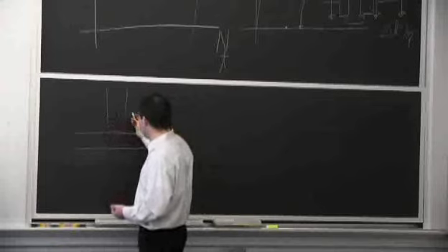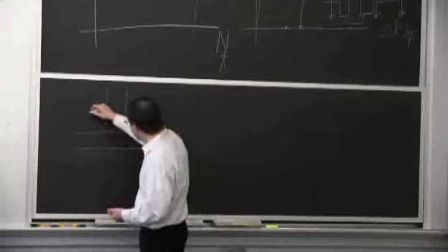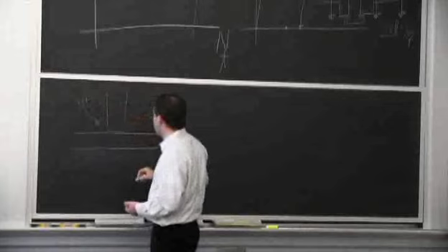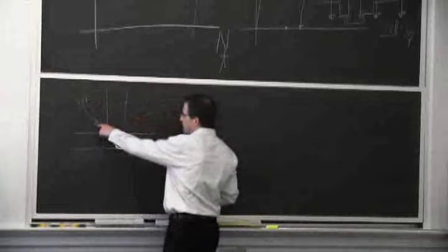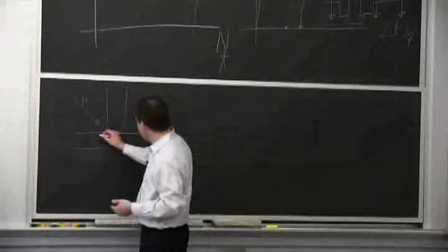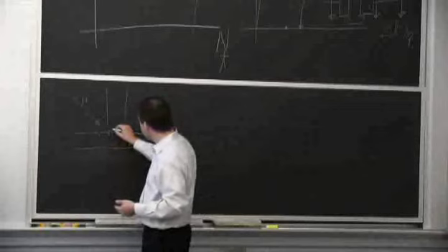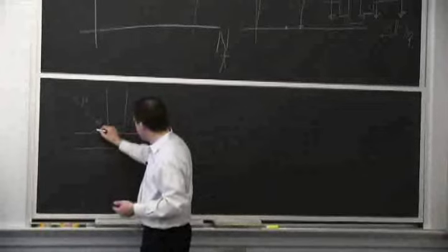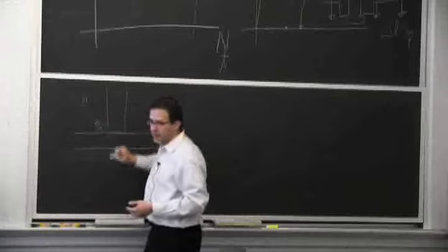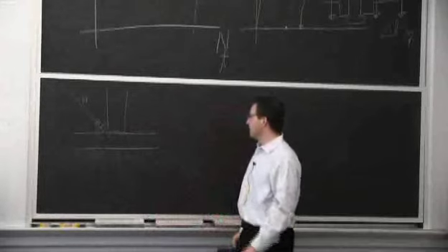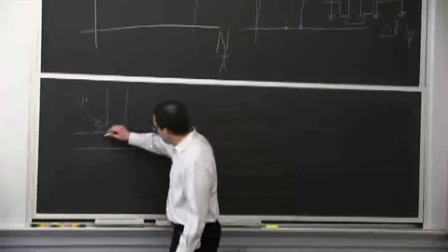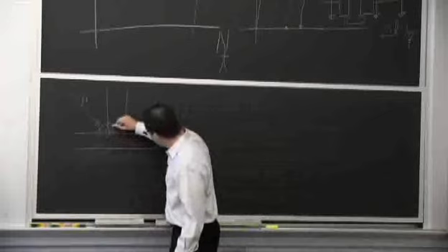But with metals, the easiest way is just say, oh, look, I'm going to come with a torch here. So I'll provide heat, a lot of heat. And my tip is also going to melt as I do it, so I provide extra material. And I'm going to melt the whole area here. So we call it the weld pool. So at some point in time, what the welder sees is this, a final geometry. It's all red. It's very high temperature. And at the end of the day, this solidifies as weld bead.